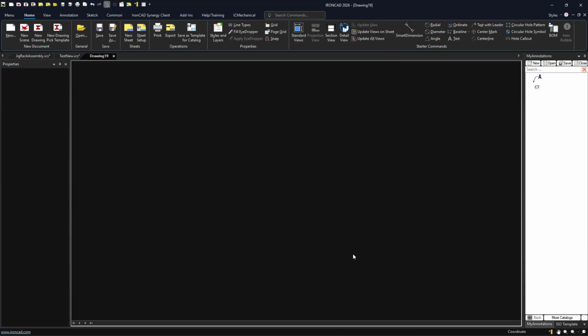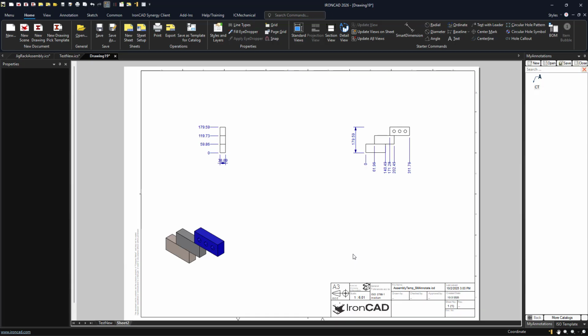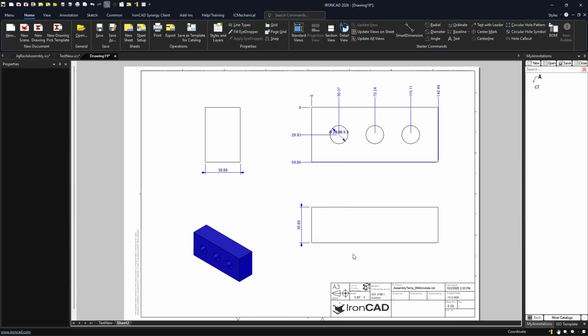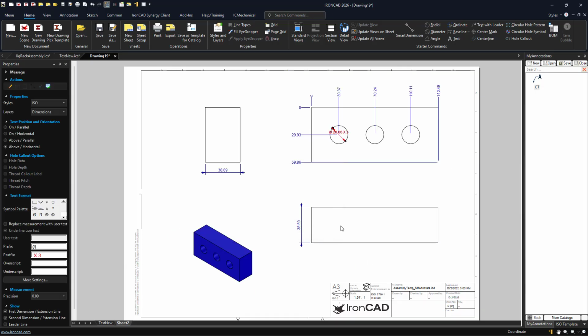So now this will run through, and again, give us a similar thing that we did for our bigger file, but I can use this anytime. So once I have my attachment points that I commonly use, I stick them in a catalog, then I can reuse and build whenever I need. So notice this is my part file. It uses the same information. I had a dimension that would call out here and here for my overall, and this one calls out my plate. So this would be a good plate drawing type annotation. So it figures out all my points that I need. Here's my origin, here's my locations there.